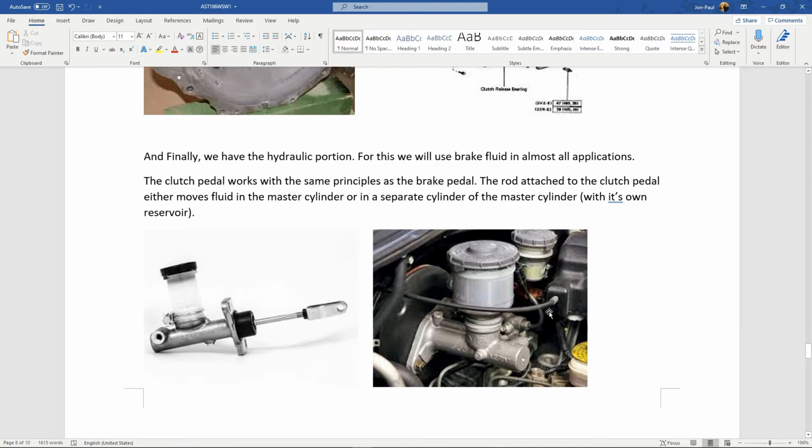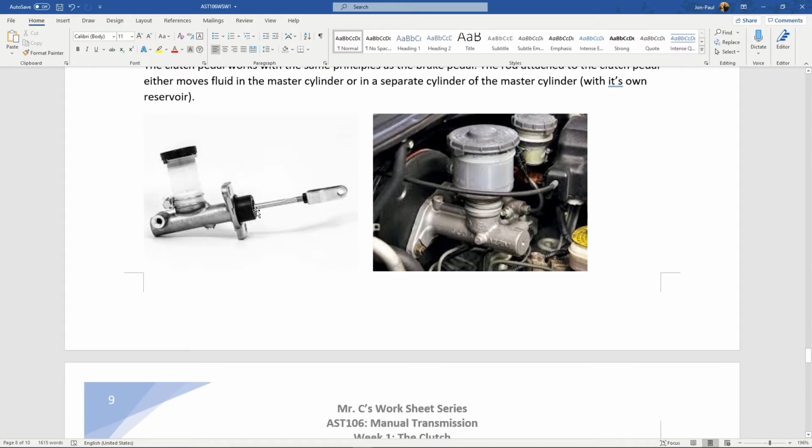So this is a great picture here. This one is the brake master cylinder, and look back here in the corner, we've got another reservoir, so that means that's the clutch master cylinder. It's very, very simple. If you've never seen one out from the side, master cylinders are so simple. Here's the rod that goes to either your brake lever or your clutch lever.